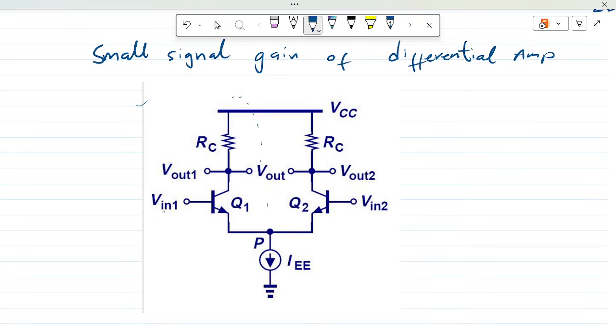Assuming the voltage Vin1 goes up by an amount delta V, then per differential signals, for the differential output not to reject the change, Vin2 should go down by the same amount, not up. If they all go up, then the change will be rejected, as we have seen.